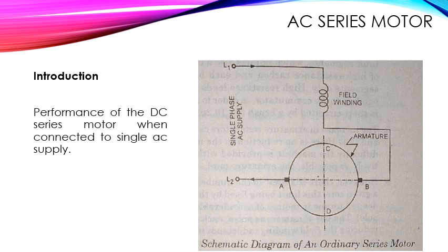It develops rotational EMF in conductors placed along the brush or Q axis due to the armature reaction flux. So the self-induced EMF, often called the reluctance voltage, is developed in these conductors due to the reversal of the current in them on crossing the brush.